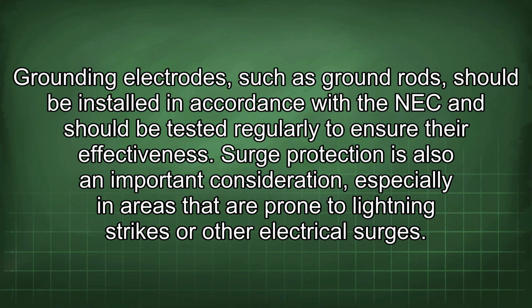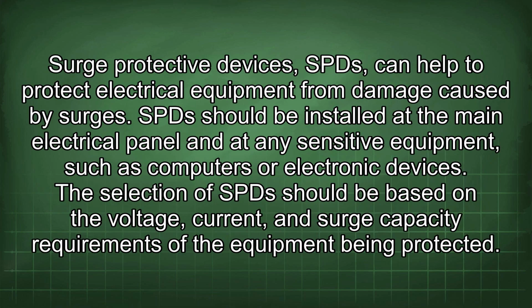Surge protection is also an important consideration, especially in areas that are prone to lightning strikes or other electrical surges. Surge protective devices, SPDs, can help to protect electrical equipment from damage caused by surges. SPDs should be installed at the main electrical panel and at any sensitive equipment such as computers or electronic devices. The selection of SPDs should be based on the voltage, current, and surge capacity requirements of the equipment being protected.